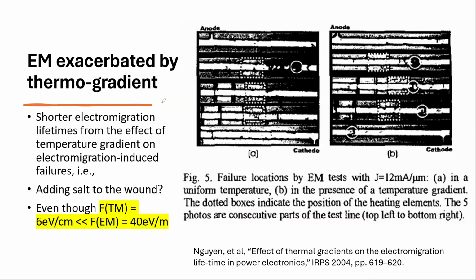But if you want to compare, besides stress, the thermal gradient, people have done a wonderful experiment. They asked, what about electromigration by the thermal gradient? It turns out that even the force from the thermal migration can be compared with the force from the electron migration. This is the electron wind. I'm talking about the force here.